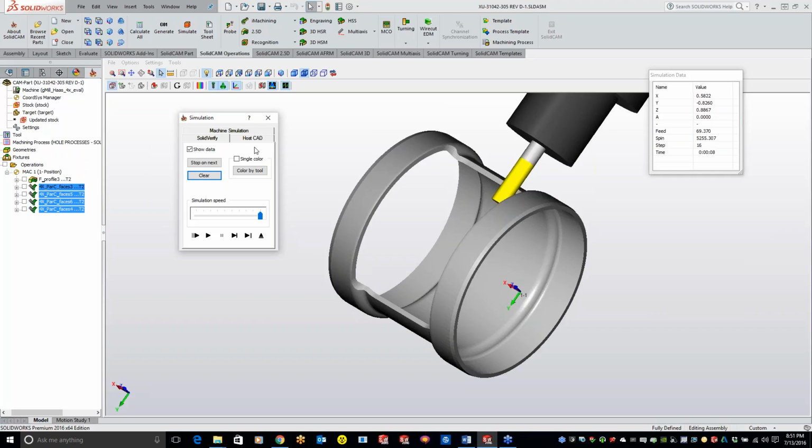Then you might even take that one step further and say, okay, at the end of that toolpath, where does that slug go? In which direction is it going to slide off? It might make a difference in how you program the part itself, in terms of where that slug goes. So absolutely, that could be useful.